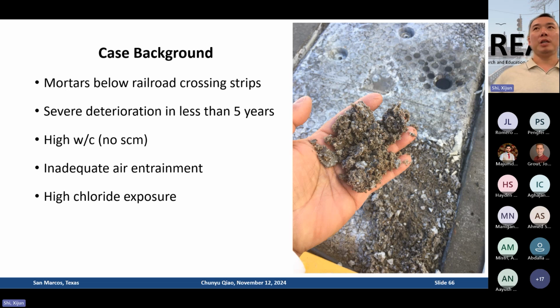After they removed the yellow warning stripes, right, that's on the platform, they saw this very white and crumbly, almost muddy concrete underneath the warning stripe. You can see they are almost white over there. They tried to core sample it for me to examine what concrete it is and what condition it's in, but they basically could not core sample because you can just use your hand to grab it. That's 5 winters after the construction.